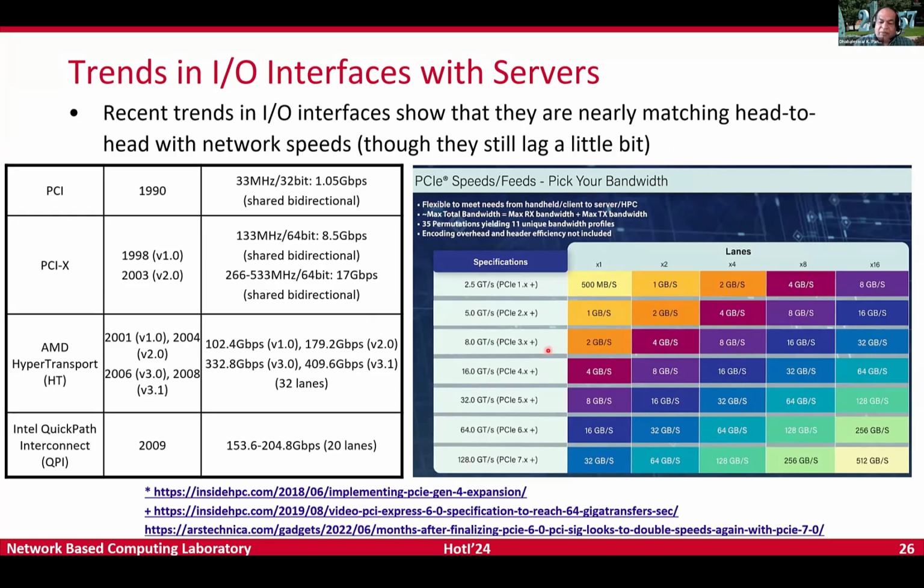But even though there is a PCI Express consortium, and of course an InfiniBand consortium, and these people are deploying the systems, sometimes the PCI Express consortium was not moving very fast. If you remember, a few years back the number one system at Oak Ridge National Lab was the Summit system. There they wanted to use multiple GPUs per node, with a high-speed network but also a good interface with the memory system. And PCI Express was not able to deliver that.